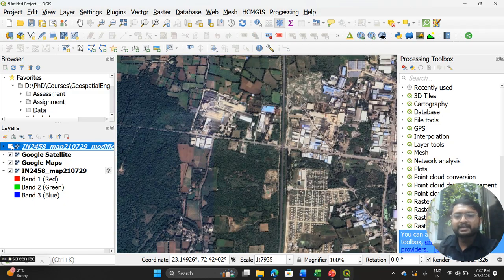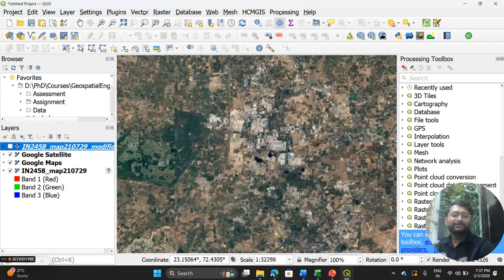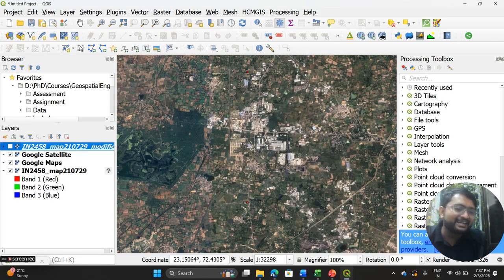Now, to avoid this kind of thing, what is actually happening in the field nowadays is, if you are doing a project and you want to get the environmental license for that project, you also have to submit the KML file of the project from where to where it is starting. If you want to create a pipeline network which is passing through a forest area, then you have to create an exact georeferenced KML file or shape file, mostly a KML file, which is easily uploaded in Google Earth Pro. So create a KML file, and then when you submit the data, you submit that KML file also